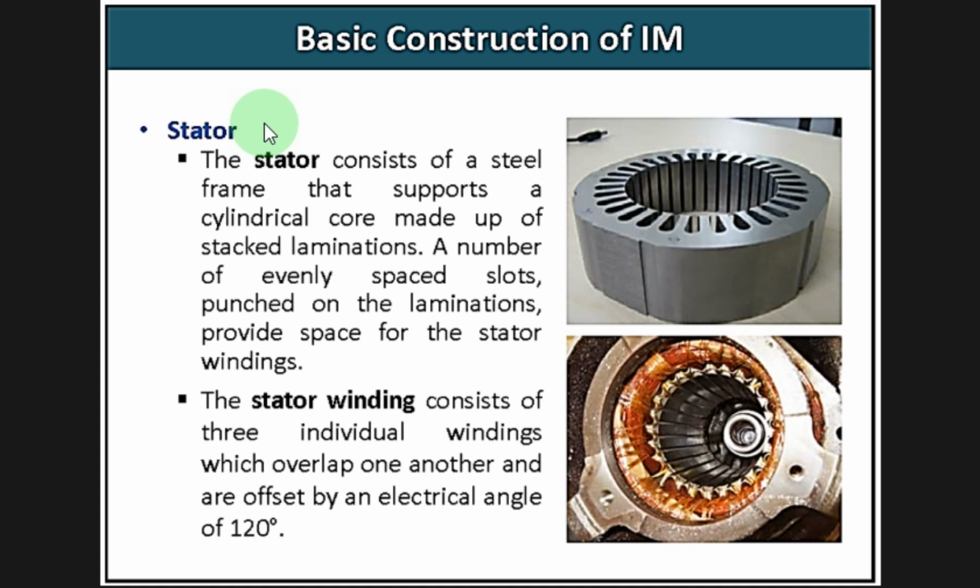So here in the stator, it has three individual windings which overlap one another and are offset by an electrical angle of 120 degrees.